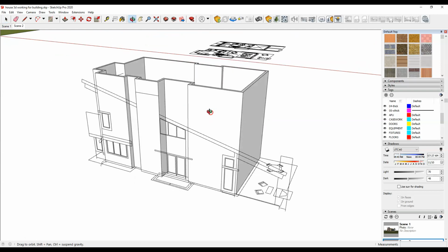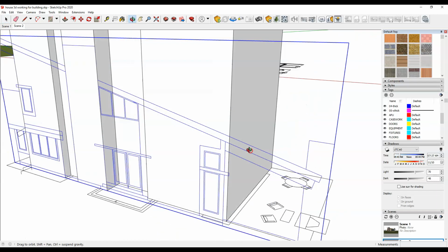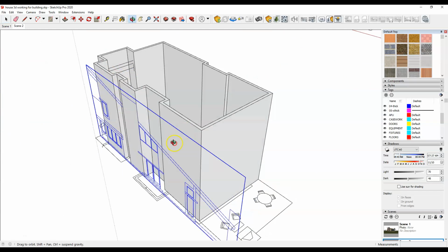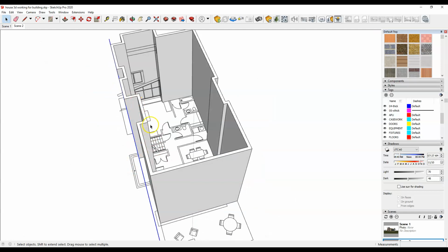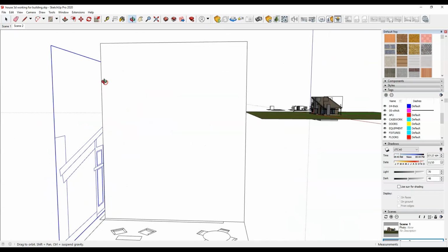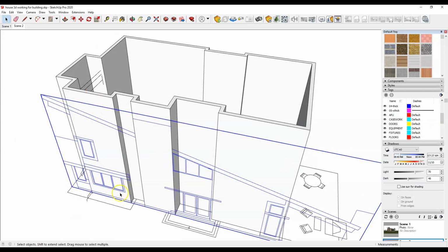And then you'll want to do your exterior doors and windows. To do that, this is where you're going to use your elevations. You're going to start in this particular house. This front wall has lots of ins and outs, and they're not aligned. This one here is the furthest in, this one over here is the furthest out. So you're going to have to move this plane wherever the window happens to be. By default, I put it on this plane here, so I'll start on this window.